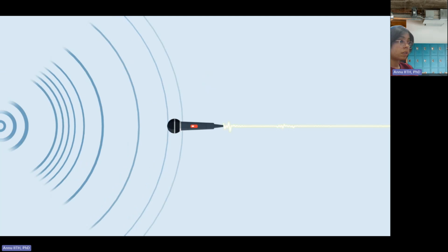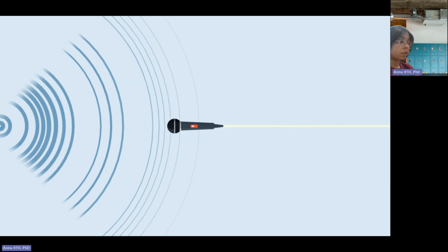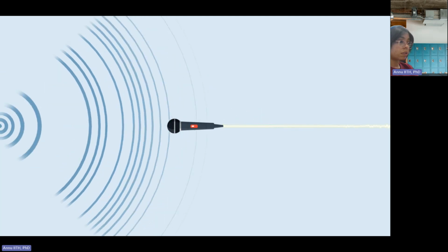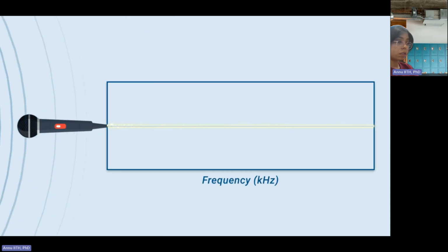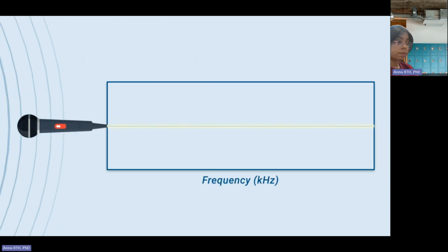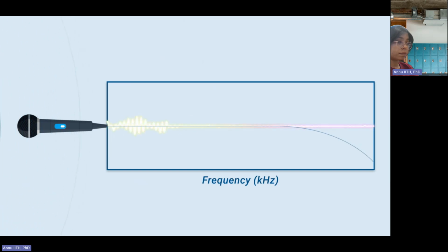And like the room, we can understand the filter by looking at its impulse response, which we then apply to the signal through convolution. For example, let's say you have a digital signal from a sensor, like a microphone picking up sound waves, and you want to filter out the high-frequency noise. This can be done with a low-pass filter, and a simple version of that is the moving average. A moving average filter attenuates the higher frequencies by smoothing over abrupt changes or sharp peaks in the signal, while leaving the lower frequencies alone.